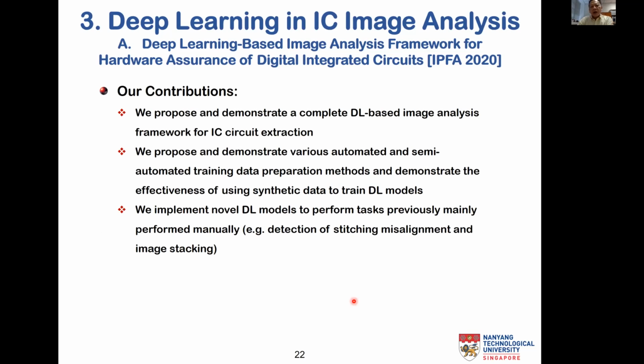So our contribution, you can look at our contribution. We propose and demonstrate a complete deep learning-based image analysis framework for IC circuit extraction. We also propose and demonstrate various automated and semi-automated training data preparation methods, which again, I will explain later, and demonstrate the effectiveness of using synthetic data to train DL models. So we can use synthetic data which is generated by us. We also implement novel DL models to perform tasks previously done manually, which again, detection of stitching, misalignment, and image stacking.